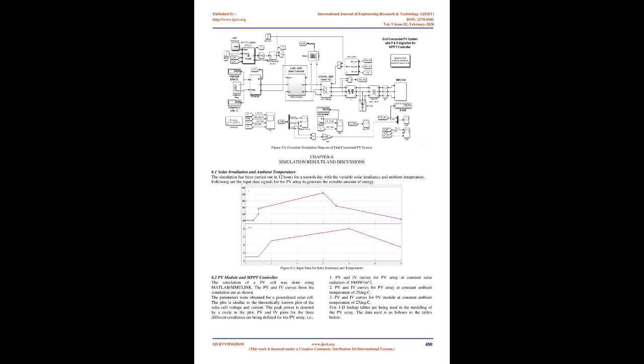Chapter 4. Modeling of grid-connected PV system. 4.1 Modeling of PV module. The simplest model to represent a PV module is the ideal diode model, presented as Rs model and Rp model. Rs model has 4 unknown parameters and is known as the single diode 4-parameter model. Similar to the ideal diode model, this model is very simple and requires minimal computation power.